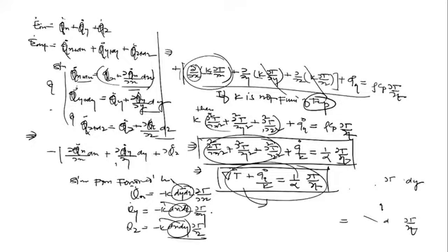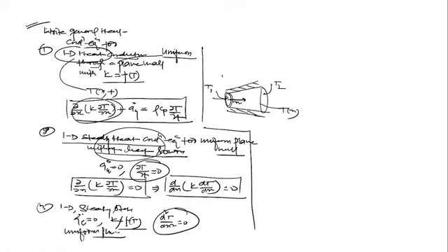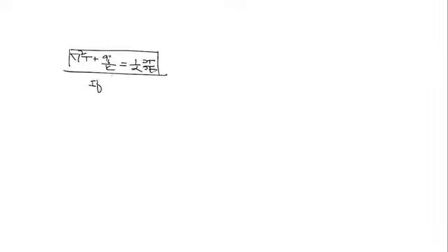So basically what I want to discuss here, listen, you must know the restriction of your equations. So the general equation that I got here, listen carefully again, is gradient square of T plus qg upon k is equal to 1 upon alpha into del T upon del t. My dear student, if qg equal to 0 and del T upon del t is also 0, means steady state, then this becomes del square T equal to 0, and that is called the Laplace equation.